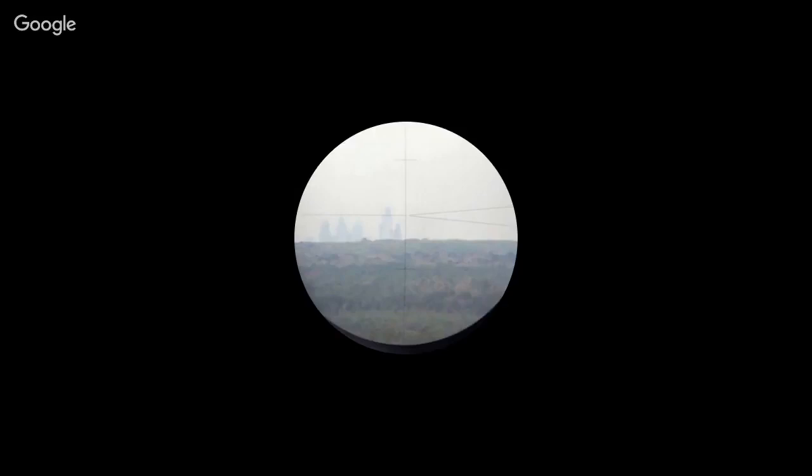And that's, by the way, back in the day before GPS, where we definitely relied on theodolite observations to measure angles. Nowadays, really, we use GPS as much as we possibly can, and then supplement it with total station measurements that are basically maybe 500 feet, 1,000 feet. That's about it.